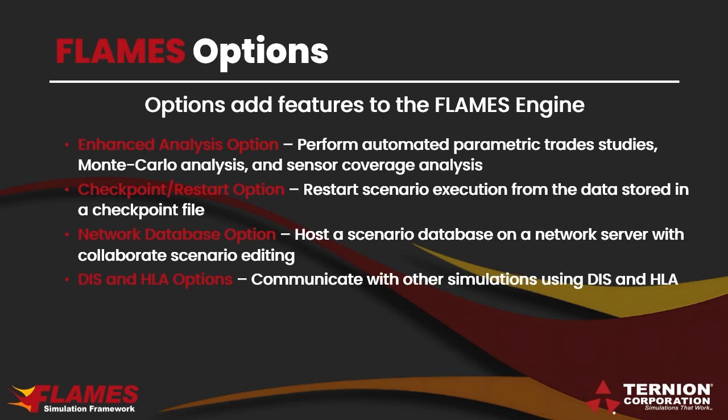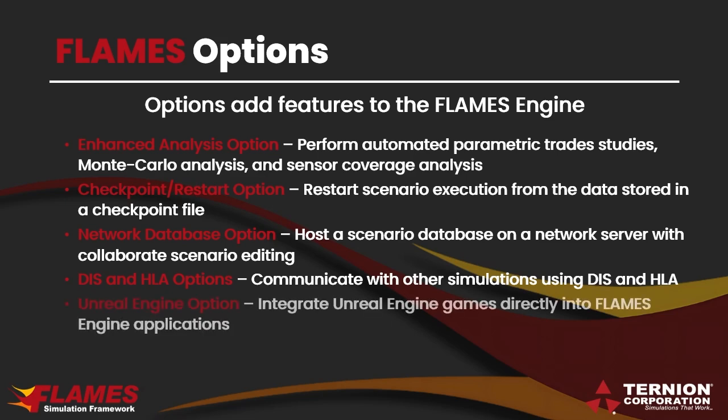You have a DIS and HLA interface for communicating with legacy simulations. The source code to how we implement the DIS PDUs and the source code to how we implement the Real-time Platform Reference FOM is also available in the Flames store. So if you want to customize or expand the way we support those PDUs or that FOM, or create your own FOM, you've got the source code to be able to do that, so you can customize it.